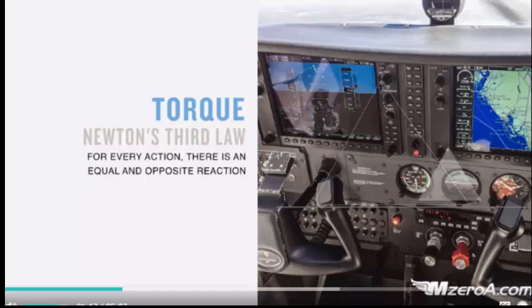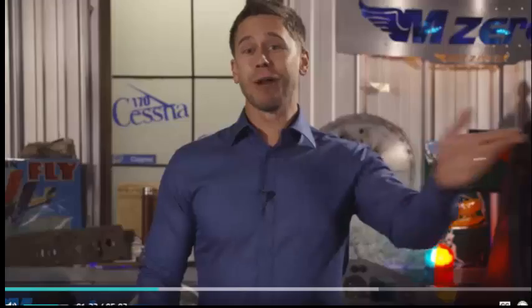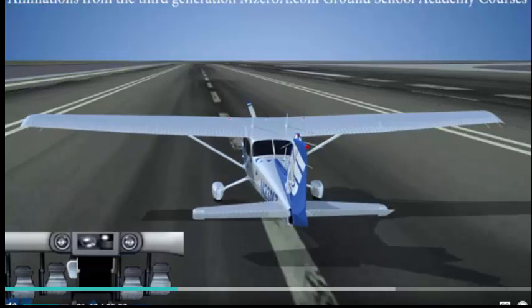Here's another one. Torque factor, which is essentially Newton's third law. For every action, there is an equal and opposite reaction. Look at this footage we captured at the Cedar Key Airport. If I apply full power instantaneously, and I don't apply any right rudder, well, where does 23 Mike Zulu end up? It doesn't end up where we want it to go, right? But when I have that proper amount of right rudder pressure, we're able to fly out smoothly here.